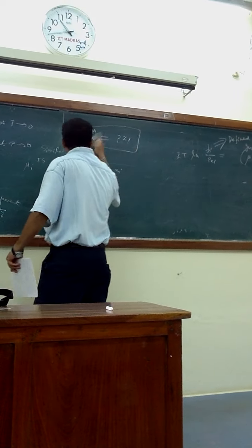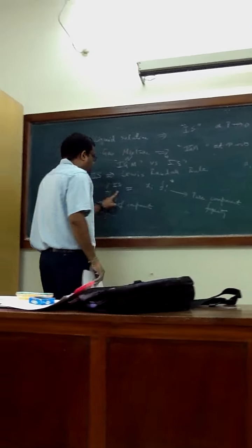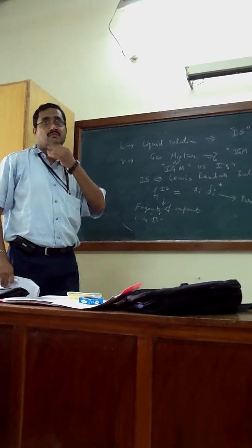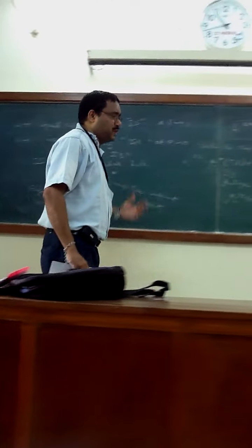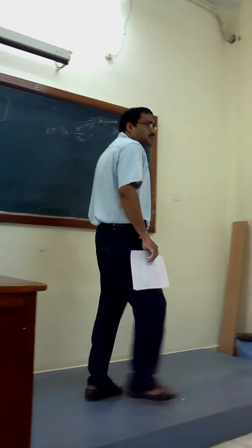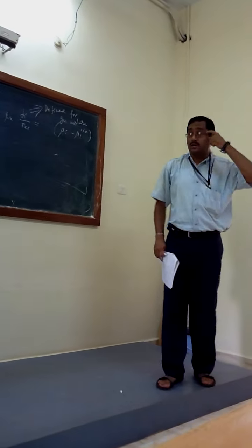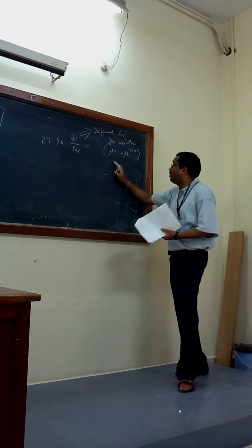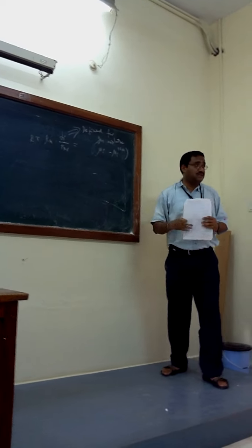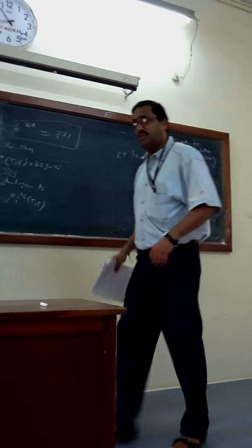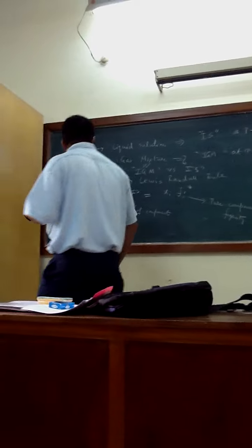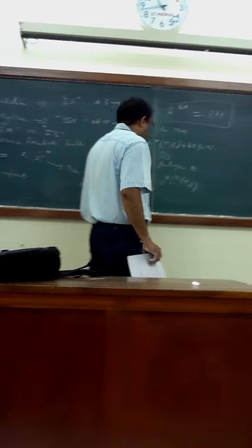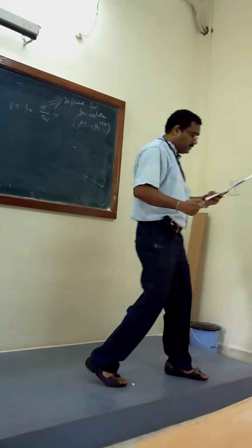For IgM we have fi equals to P xi, while the Lewis Randall rule says fi equals xi fi star. Remember that fugacity is based on the gas or gas mixture, because the definition is based on gas mixture. You cannot say fi is equal to P xi, because we don't know what the departure of mu i minus mu i IG is. We don't know. So the basic definition is there, and for the Lewis Randall rule we have to apply fi equals xi fi star.